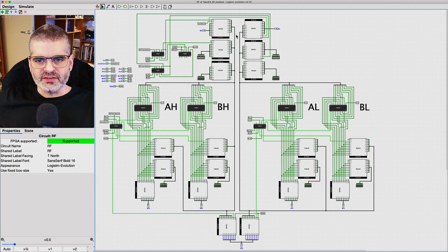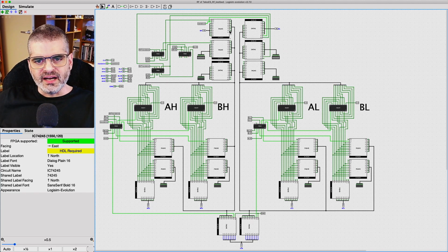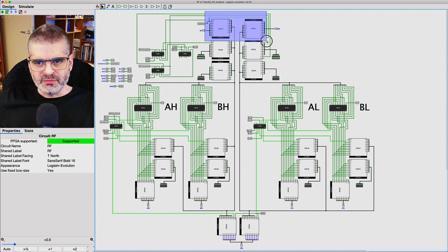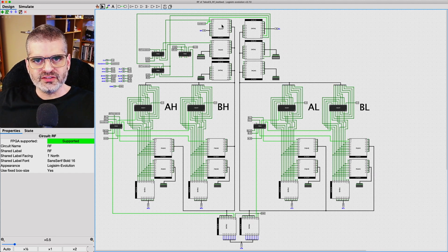To connect the local bus to the internal bus of the other cards through the backplane connector, we have these two extra buffers here on top. And they can either drive the contents of the local bus out to other cards, or they can drive the contents of the internal bus as defined in other cards into the local bus here. So the direction bit is no longer grounded. The direction bit now of these two buffers here is programmable. So we can determine whether the local bus is transmitting or receiving information from the internal bus of other cards.